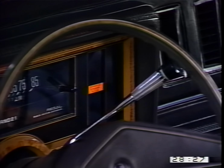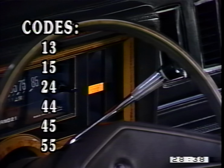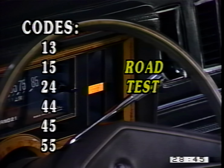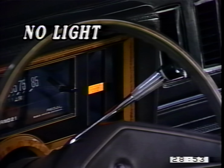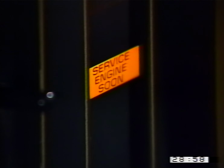If the light comes on, enter the diagnostic mode manually, reading and recording the trouble codes. What you will be getting will be hard failure codes. If you had previously recorded stored codes 13, 15, 24, 44, 45, and 55, you may need to road test the vehicle in order to reset the hard failure after clearing the trouble codes. If you don't get a service engine soon light, all the stored trouble codes are probably intermittent failures. Now, when the light comes on but doesn't stay on, there may or may not be a trouble code stored. You've got an intermittent problem.